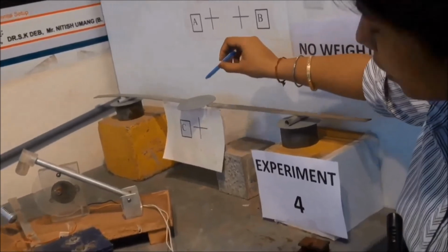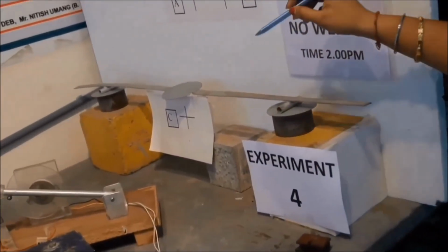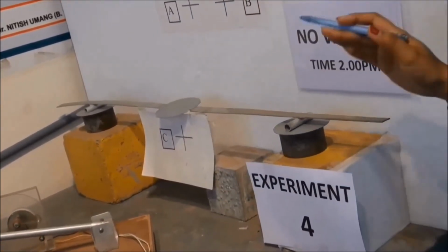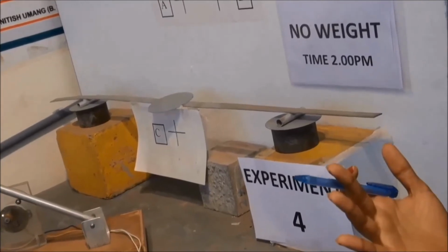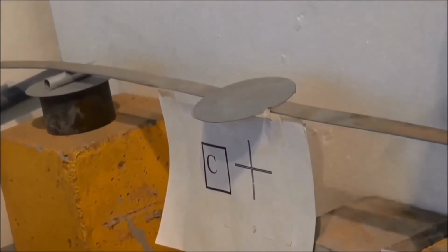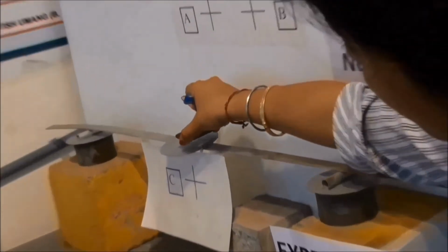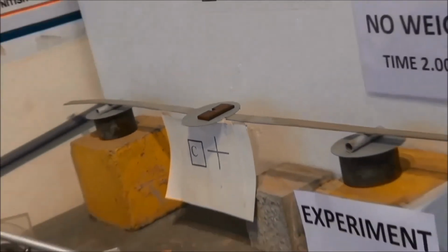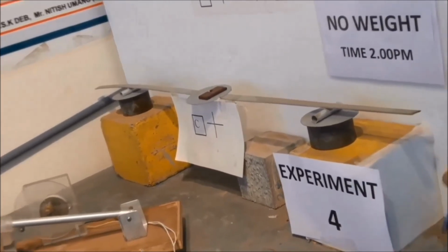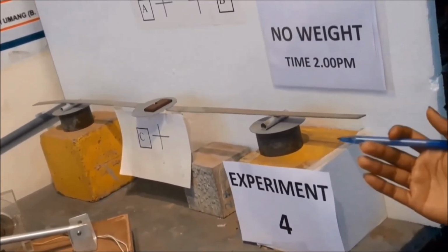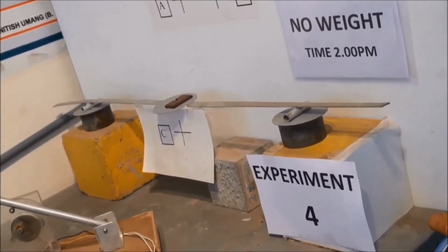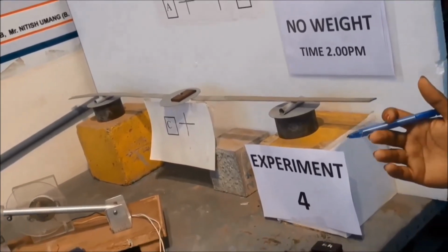We will capture the picture of this whole setup in basically four situations. First is the no weight case, when this beam is not loaded. Then we will keep on adding loads at fixed intervals of time, like we will be adding loads at 1 hour. So this experiment is being repeated twice a day. So first 4 conditions at 1 hour interval in the first half and similarly in the second half.